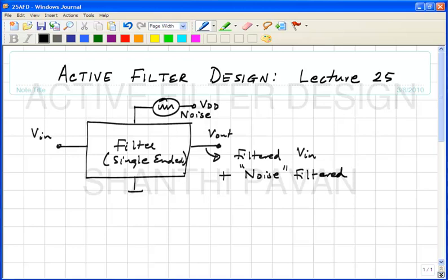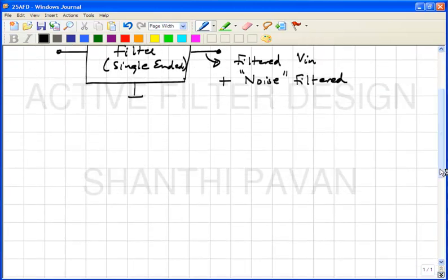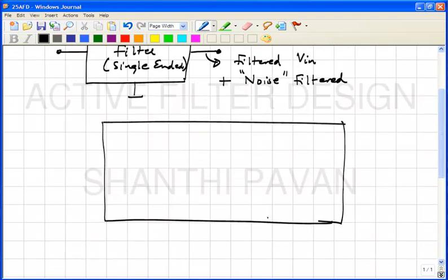So like that. Now, is this noise in the supply a far-fetched situation, or is it, do you think, a reasonably practical scenario? It's reasonably practical simply because this filter most of the time is not sitting in a showcase. It's being used as a part of a big mixed signal chip, right? So as I indicated to you in the very beginning of this course, this filter is a part of a big chip. Perhaps there's a lot of analog, there's a lot of digital, and this is all part of the signal conditioning electronics, right?